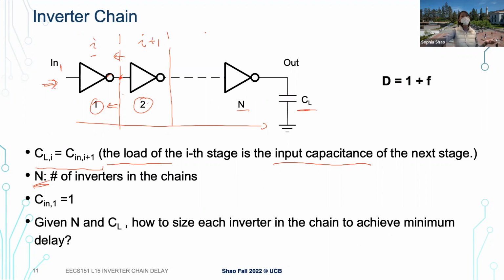And when we want to make our circuit faster, fixing the critical path delay of our circuit, we can also remove different modules, but that's a different discussion. Here, in particular, we think about transistor sizing. With this setup, given this chain and given this load capacitance, we have this flexibility, assuming the circuit is fixed now.